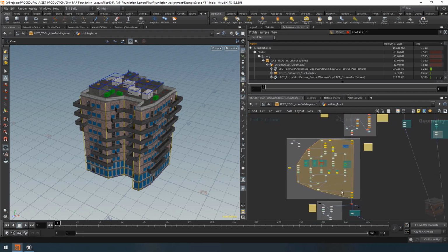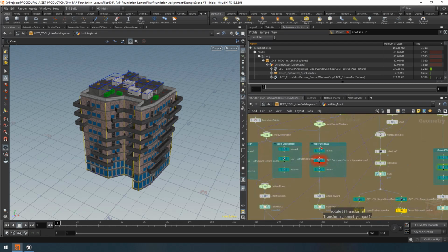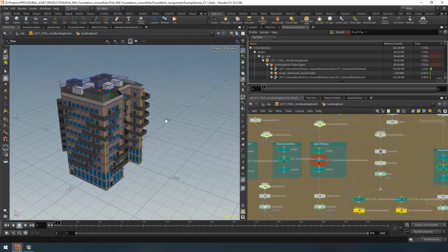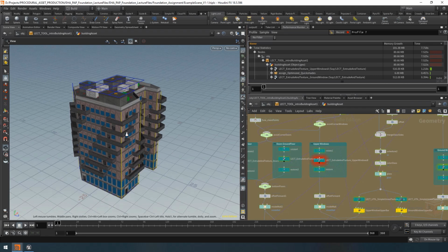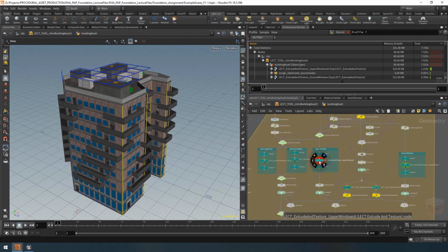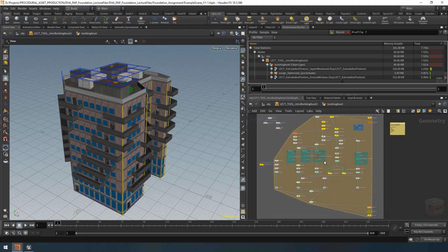Now in this case, this node resides here, inside of our for each loop, and it is part of the windows. Now that's probably because most of our tiles here actually are comprised of windows. So it's kind of a biased readout. We could consider that there are more windows to compute, therefore this node is slower. But we also need to consider why it's slow.